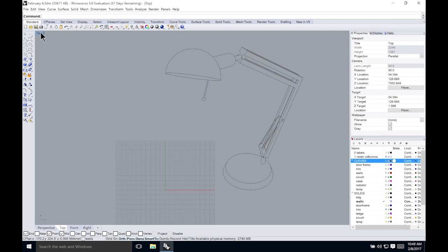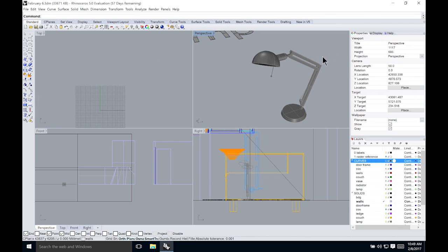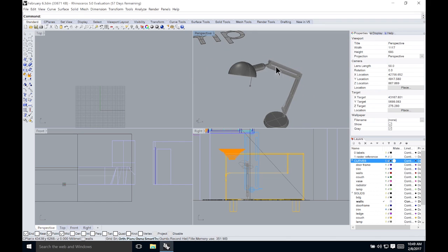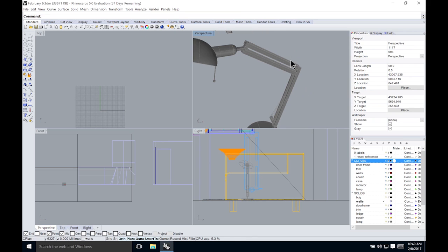What I wanted to say, and I guess this just didn't turn out to be a good example, is that sometimes following a Boolean operation there is an extra step necessary to get rid of extra lines, and that is called merge all faces.